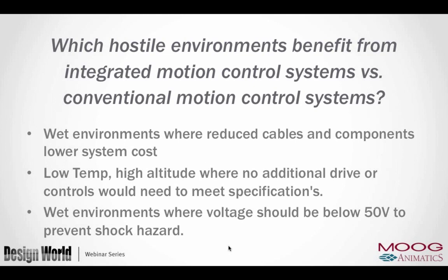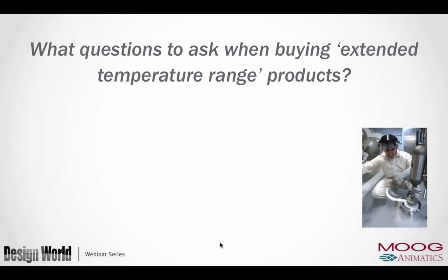You don't want somebody getting shocked when they touch the cables if it did happen to seep in through the cables. Now, I will say that there's some little tricks you might want to help yourself with on there. You have to seal those connectors on any motors regardless with a dielectric grease just to prevent anything from causing a shock through conductive liquids.